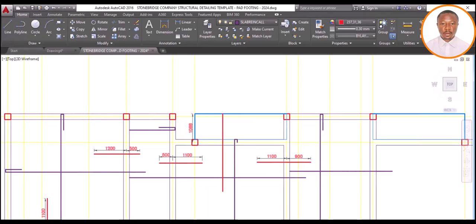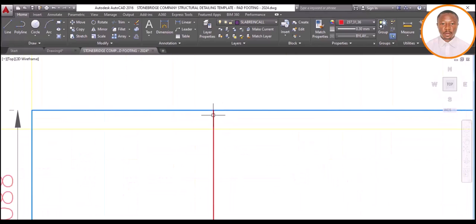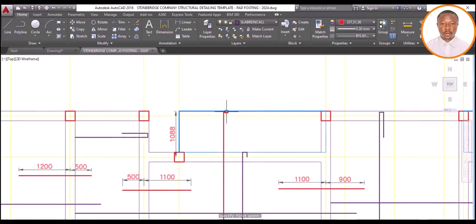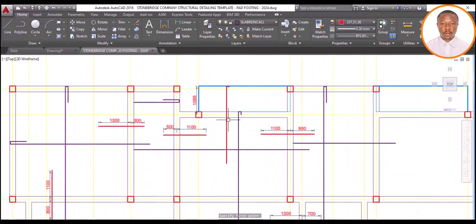And let's see, this becomes my member. Then we can now remove our concrete cover, which is 25. Enter. Then 25. Enter. Have our reinforcement of, let's say, 100. Yes, 100. Then I have this. This becomes my top reinforcement. So do we get it now?